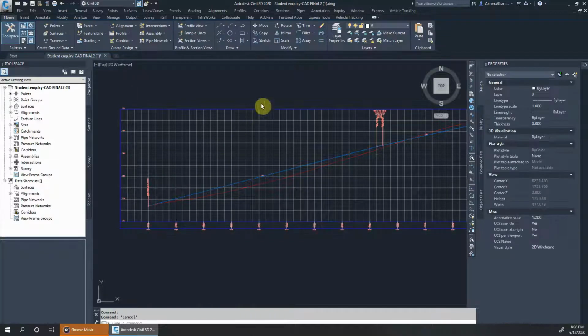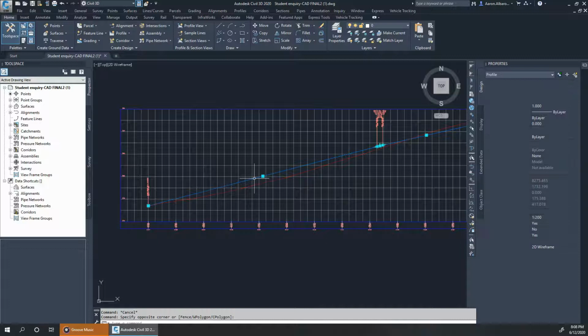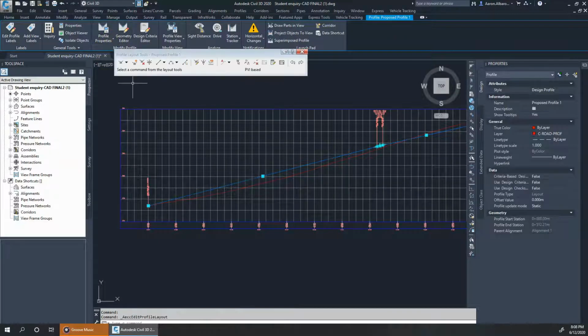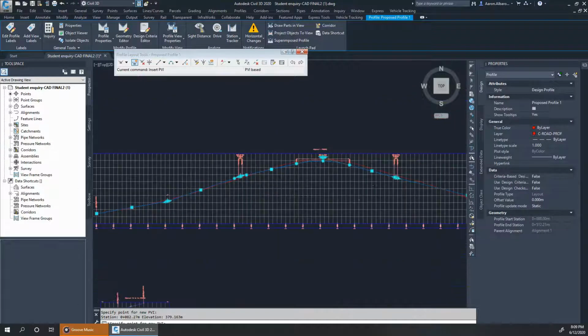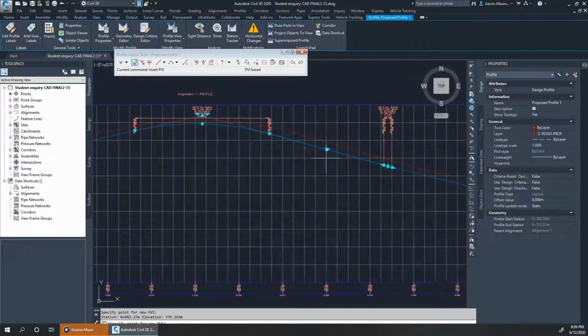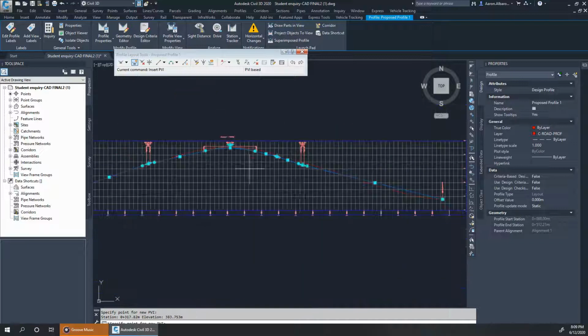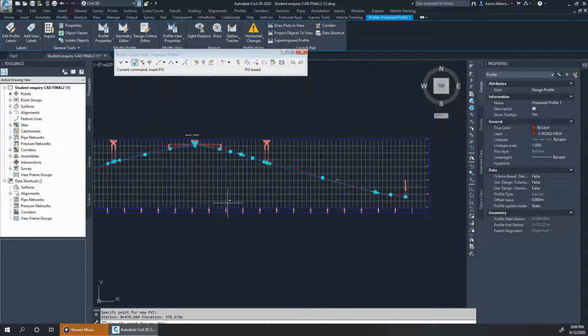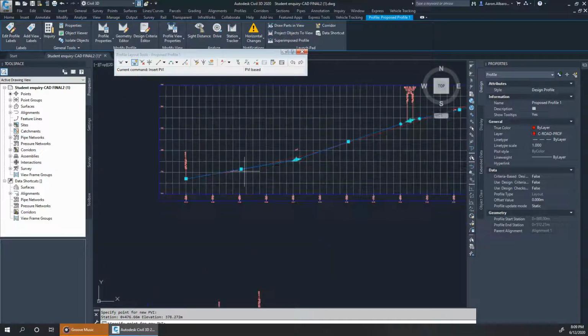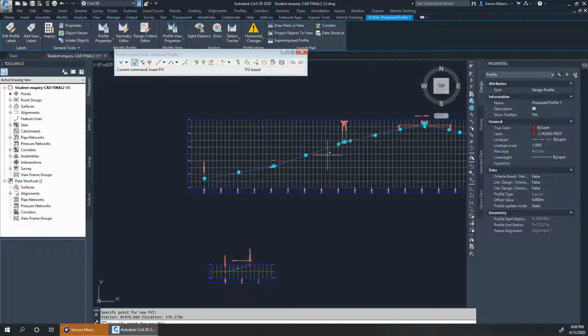By clicking on the profile here, on the vertical profile, if I click on geometry editor, that will allow me to add extra vertical points. So if I add these points, I think the profile should go to this point here and then go up. So I'll add a point around here, and we can amend that area in a minute. I'll add another point around here to come closer to the surface, and maybe a point around here should be added. Okay, these are the points that I think we still need. If we find that we need more points, we can add them in a minute.